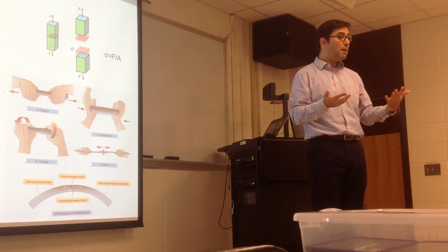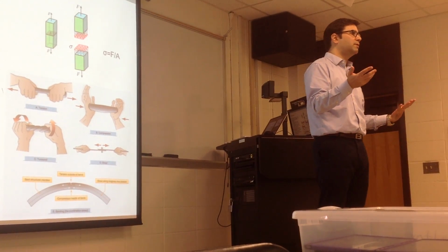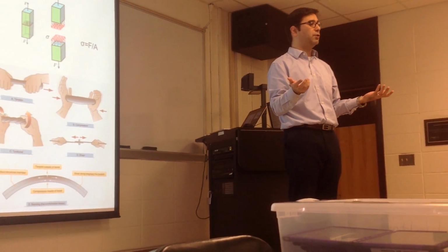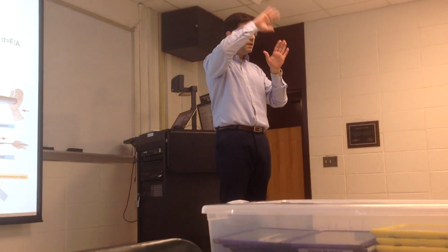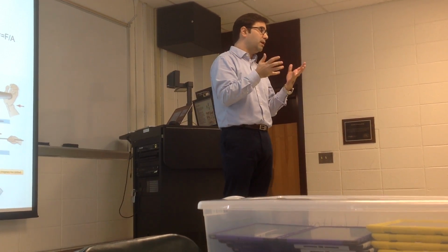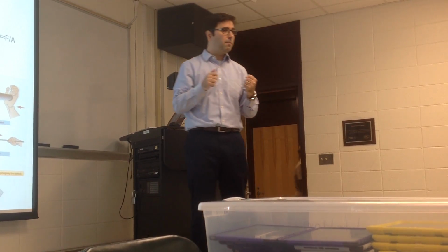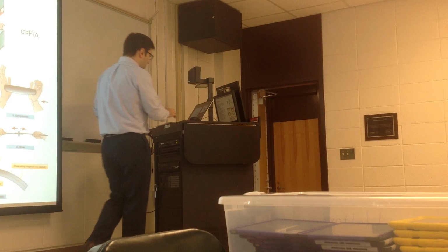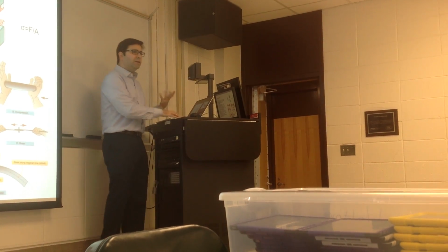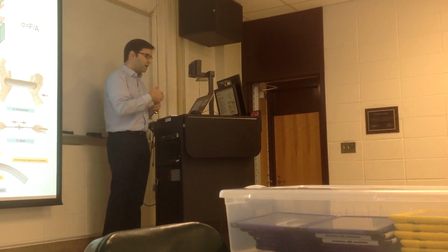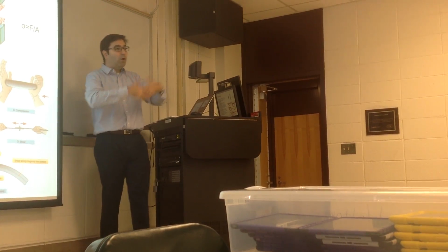Some materials behave differently under certain stresses than others. For example, ceramics that we use for thermal barrier coatings in the discs in the hot area of turbines, where you cover the material with ceramics so it doesn't get that hot. Those ceramics are usually really good under compression. But if you apply a tensile load, they will just break apart.